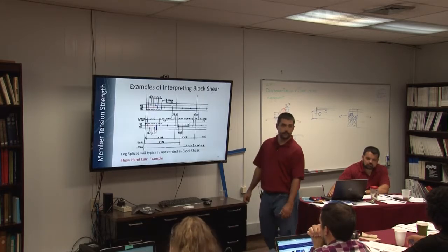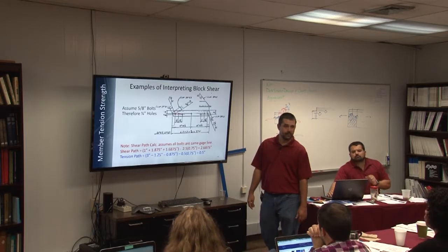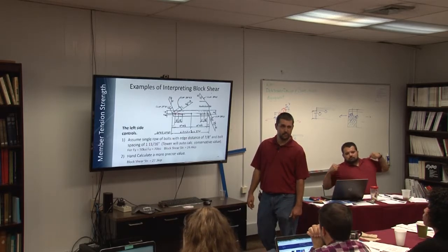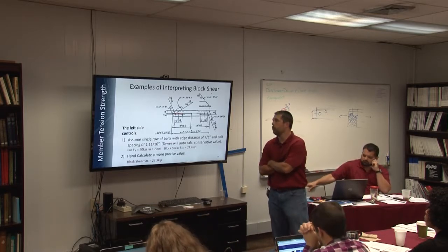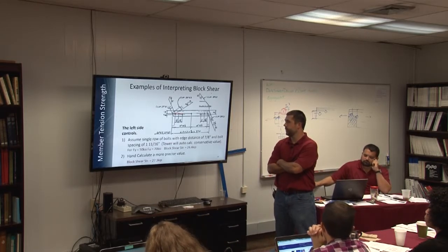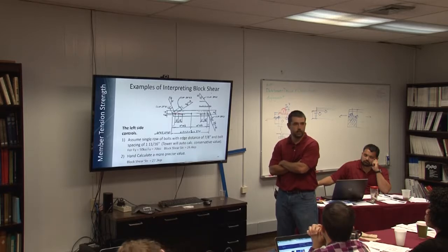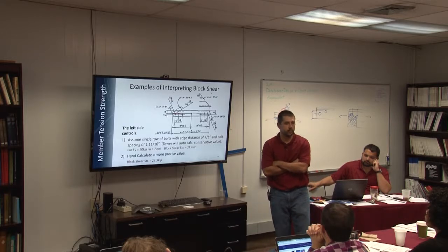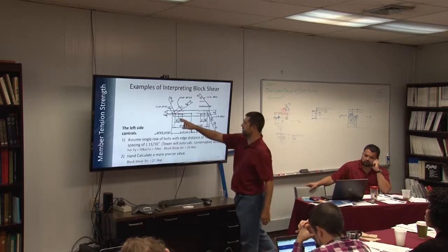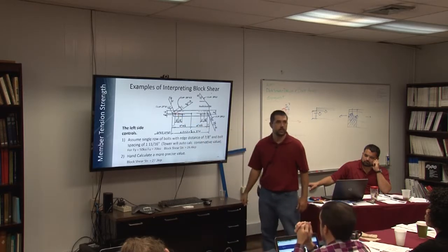So, do you typically do that by hand and then compare that, like you said, to the bolt and then just ignore that? What we typically do is calculate these lengths by hand and just drop them into the program. And by hand, I mean, again, we do this enough that we've taken the time to develop a spreadsheet to get these numbers for us. So we define the different bolt spacings and things.